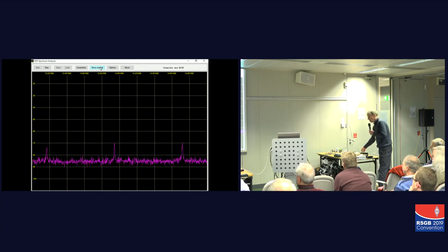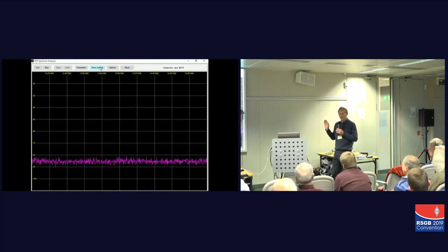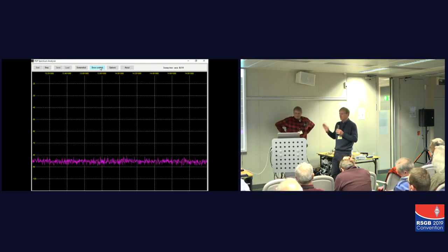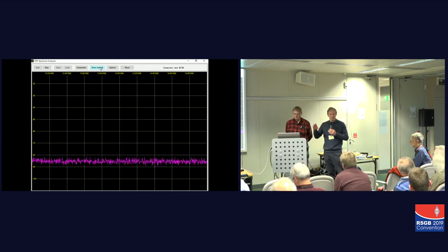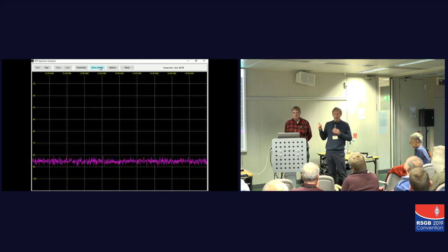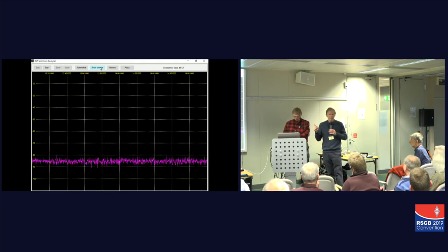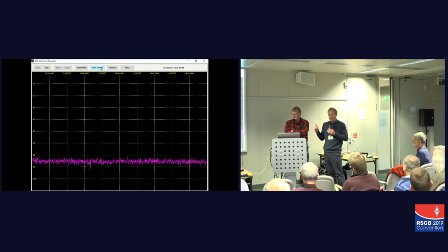But you'll know if you've got one of these because it's been in RadCom, and when the audio amp is in use, because it's pulse width modulation, if you listen on AM, you'll hear the audio that's being transmitted by the Class D amplifier. In fact, when we first came across this, the person who reported it thought it was an HF broadcast station operating in the amateur band, but it wasn't. Not an intentional broadcast anyway.